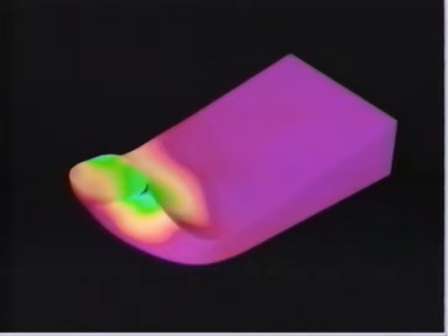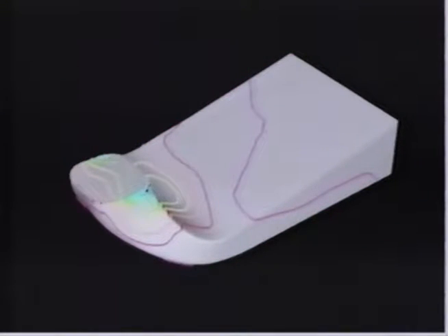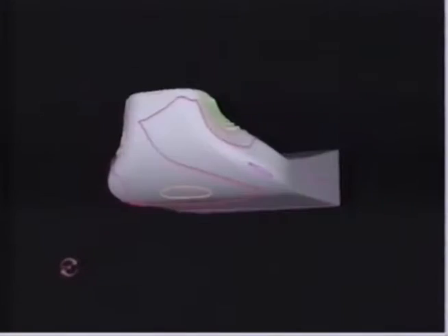Color here is attached to the pressure distribution. Color mapping can be switched from smooth interpolation mode to banded mode. The computational grid can be displayed over the pressure map surface, or contour lines in pressure can be displayed over a shaded representation. For any of these displays, a switch to the view control mode allows for interactive positioning and inspection.